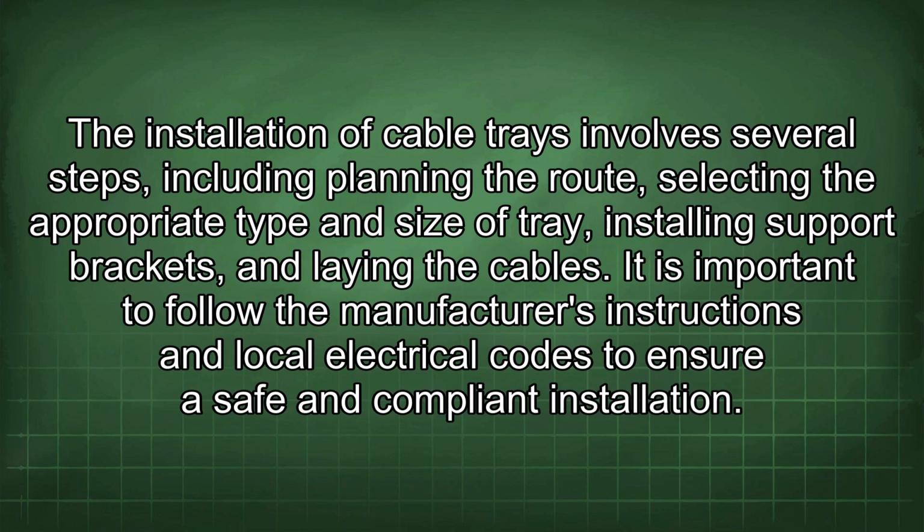The installation of cable trays involves several steps, including planning the route, selecting the appropriate type and size of tray, installing support brackets, and laying the cables.